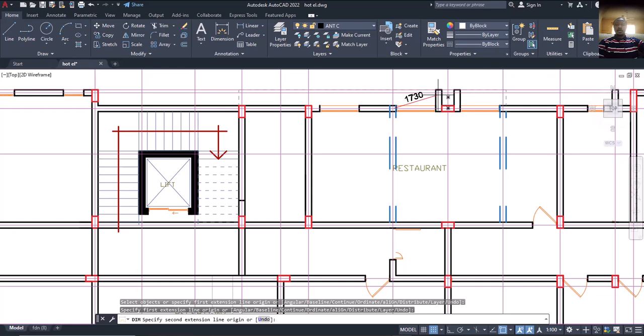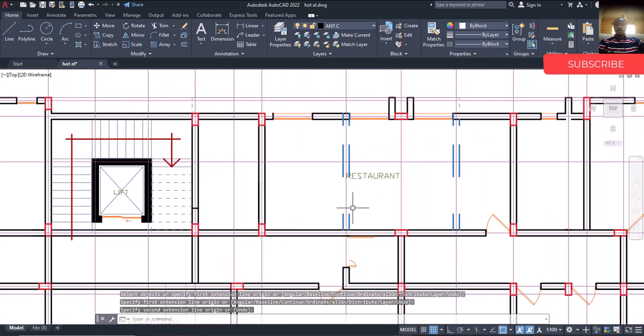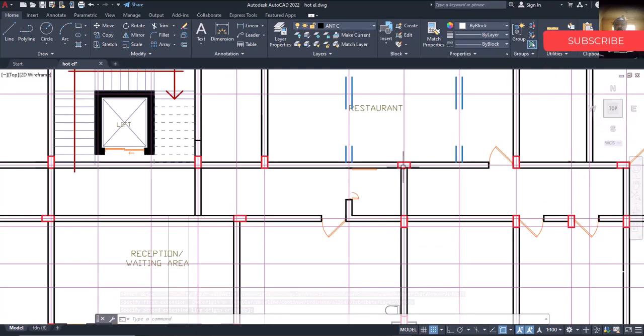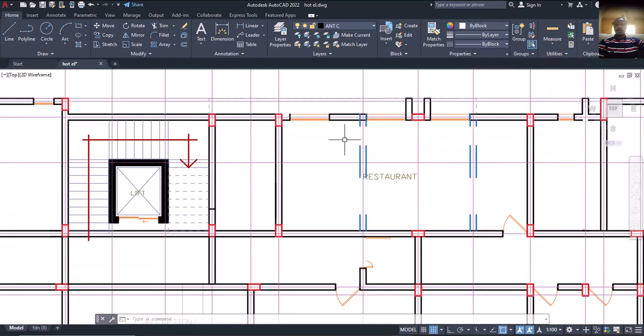this one is just a dot. We can use a small beam to achieve this, or even a slab. A slab can achieve this one for us. Let's see. We can put a small beam here, a beam here. Okay, so we can try to put a column here, at this point and at this point, which means that in this place there will be no column here. Is that okay? So I think that one is better for us.